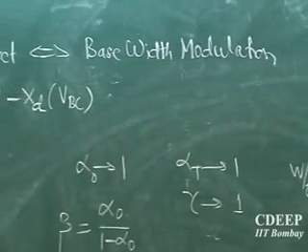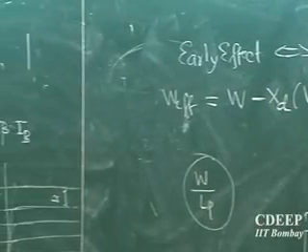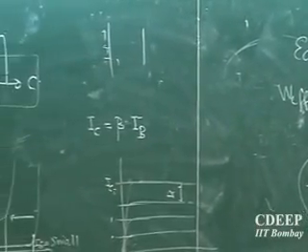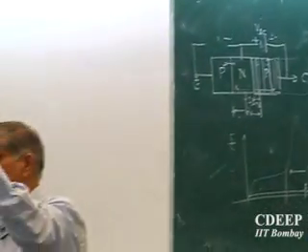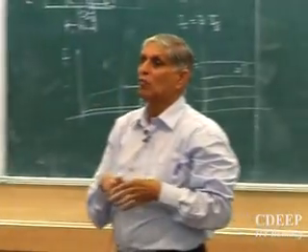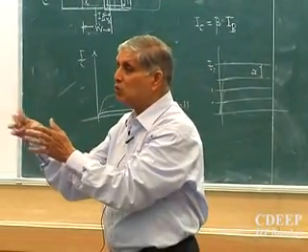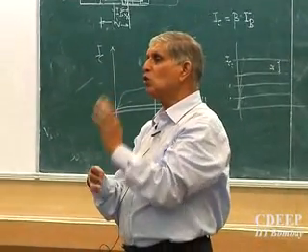So sometimes a larger base current can change the breakdown characteristics. So the uppermost limit, for a given base current, what is the maximum breakdown you can attain? Is that clear? This is also one limitation which the device has to bear, because in a circuit you must obviously know what is the maximum value that I can use, and what you should actually use.